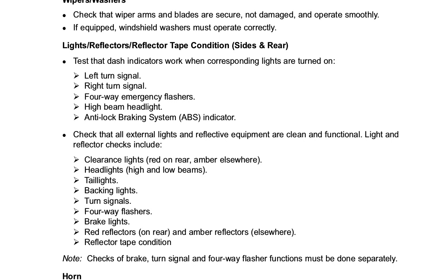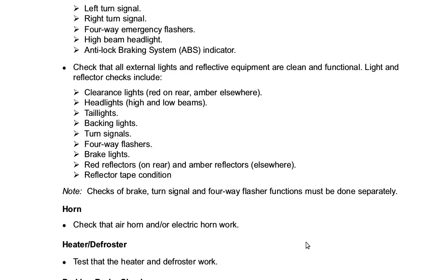Tail lights, backlights, turn signals, 4-way flashers, brake lights. Red reflectors on rear and amber reflectors elsewhere. Reflector tape condition. Note, checks of brake, turn signal, and 4-way flasher functions must be done separately.